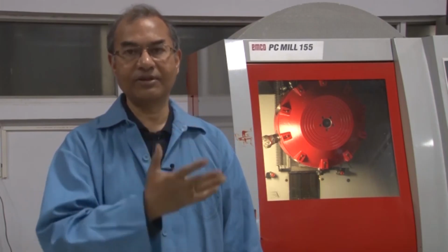Similarly, there are digits from 0 to 9. There are points, plus and minus signs, and so on, and each of them indicates something. For example, if you have to change the feed, you symbolize that as F. If you have to change the speed, you symbolize that with the letter S, which stands for speed, and so on. Overall, each letter and each symbol means something to the machine. The machine has to understand this language or these codes.